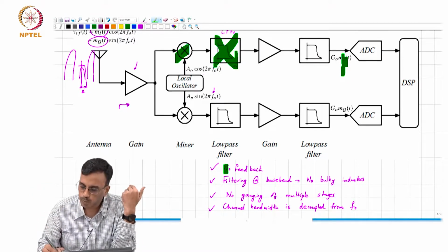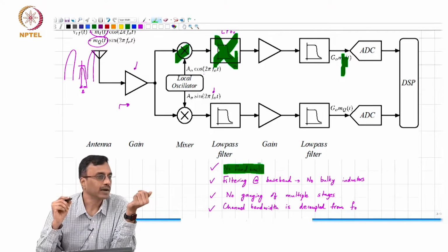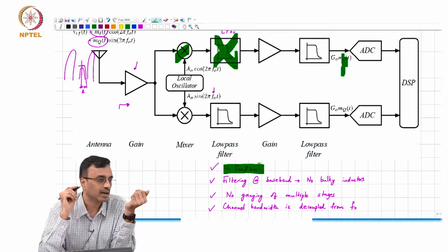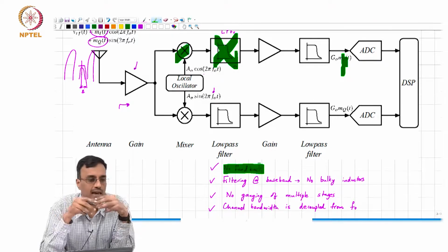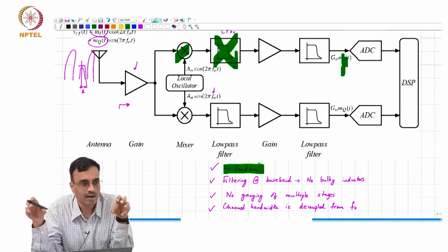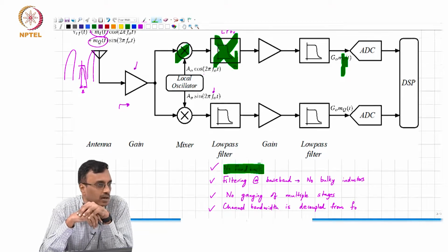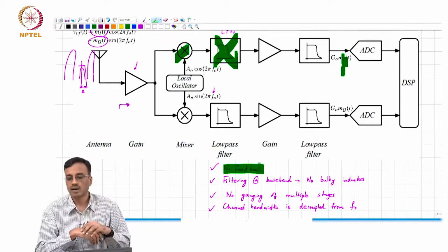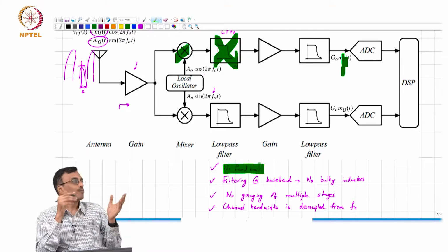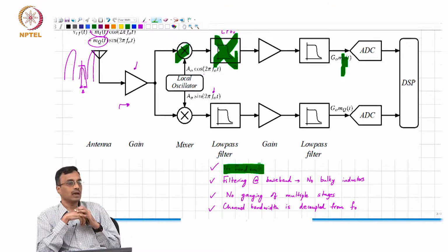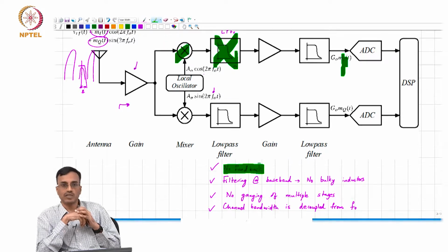So, there is no spurious feedback, which can kill us, because most of the gain and selectivity is obtained at baseband, where isolation is fundamentally much higher. The center frequency of the effective band pass filter that you are making is set by the frequency of an oscillator.